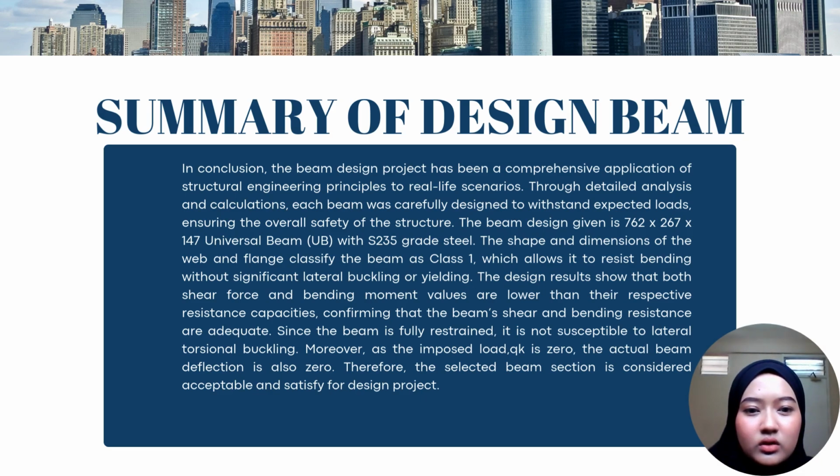The design results show that both shear force and bending moment values are lower than their respective resistance capacities, confirming that the beam's shear and bending resistance are adequate. Since the beam is fully restrained, it is not susceptible to lateral torsional buckling. Moreover, as the imposed load Qk is zero, the actual beam deflection is also zero. Therefore, the selected beam section is considered acceptable and satisfactory for the design project.